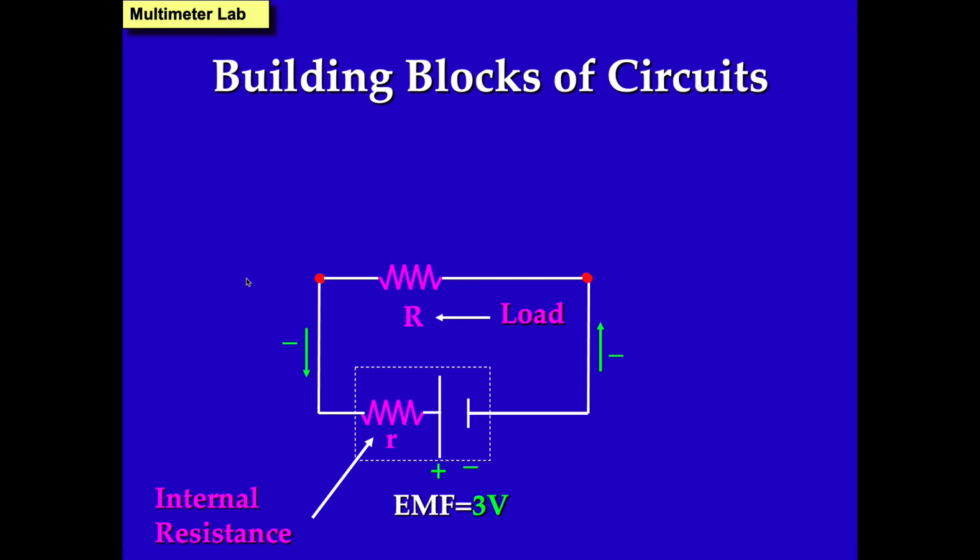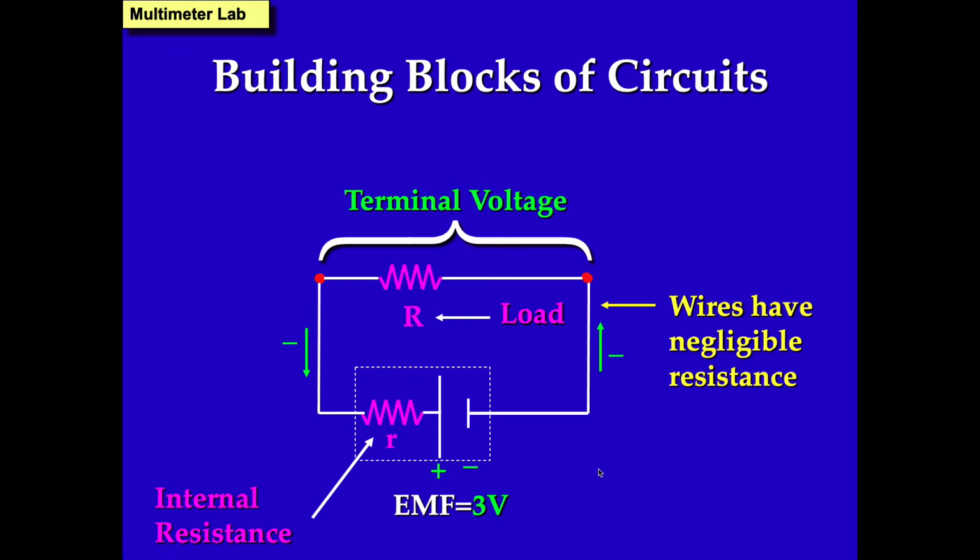And as that R gets bigger, the voltage across your load gets smaller until eventually, if that's a light bulb, the light bulb won't light up, and you recycle the battery. That's because your internal resistance is getting higher and higher. So really, what the load is getting is something called a terminal voltage. That's the actual voltage across the device, and we'll talk about how to make the measurements next week. So the voltage across the device is called a terminal voltage.